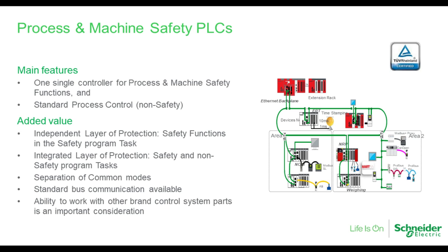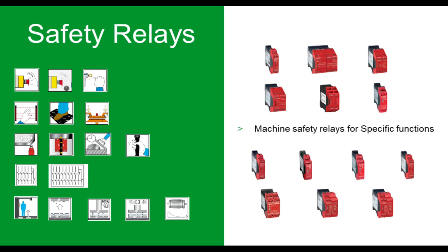Or the application is actually installed on site. Very typically, you're going to be dealing with a safety PLC in that application because of how closely they're tied together, and also because cost is usually less of an issue than it might be when you're a machine builder who is trying to sell machines to a customer. And then you'll usually see a safety PLC on installed on-site kind of applications.